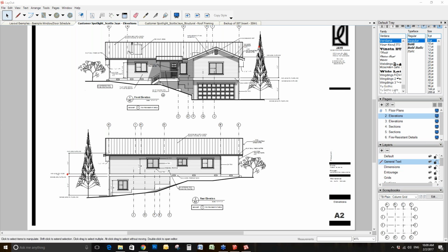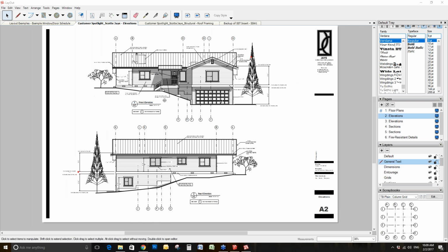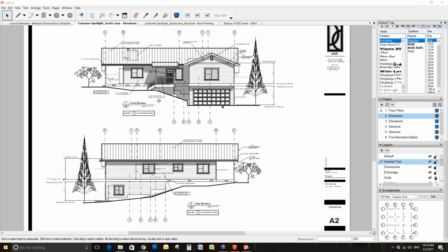One question is, yeah, so previously, before SketchUp Pro 2017, in Layout, if you were spending all your time setting up your line weights and your drawings and your hatching, but then you needed to export to DWG so you could consult with your consultants, etc., the output was not great. And that's been one of the vast improvements of SketchUp Pro 2017, is that now your layout drawings, everything you do, your line work, your line styles, hatching, masks, everything, you can then export into a DWG format, and it will be exactly the same as what you've done in Layout.